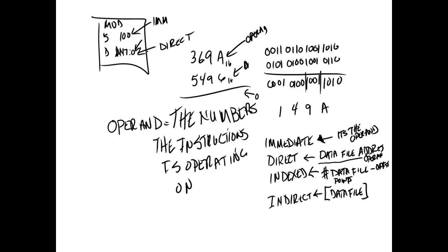So these will be on the test, the addressing modes for this microprocessor, or for this PLC, the Allen Bradley PLC. Now, what addressing modes does it support? These are the ones that RSLogix 500 supports. The ones that actually are supported by your PLC would be in the information about the PLC, right? So the 1100 doesn't give us access to the index register because it always starts with 0. We don't have any instructions on the 1100 to set the index register.